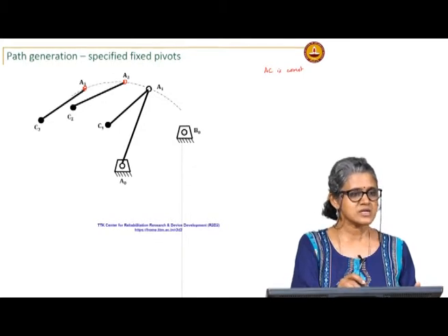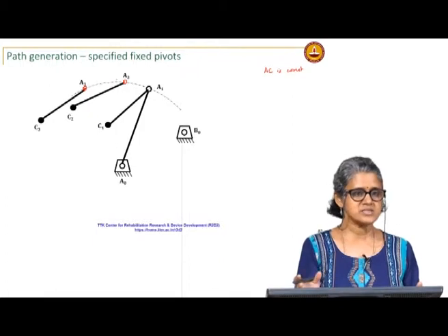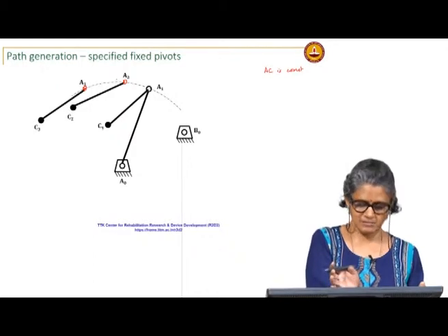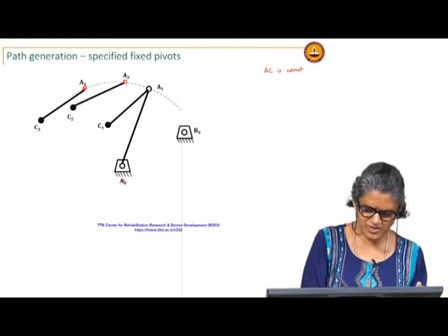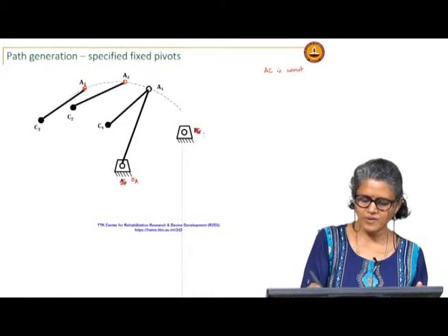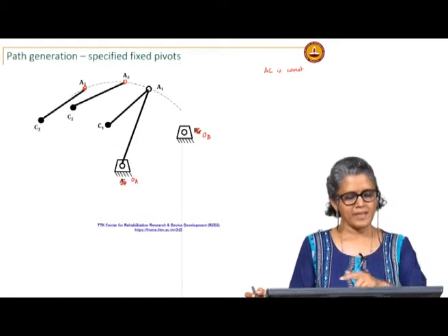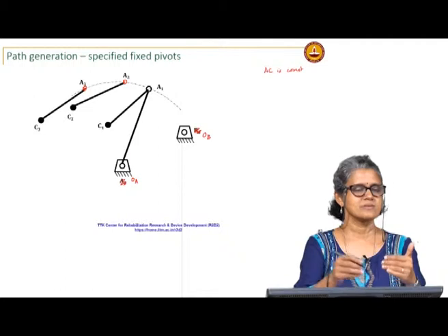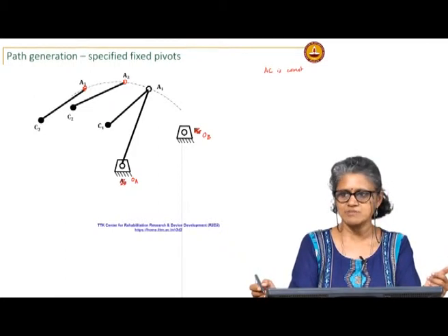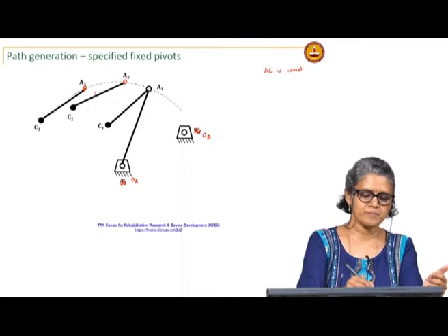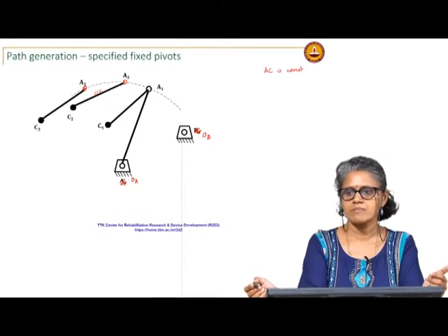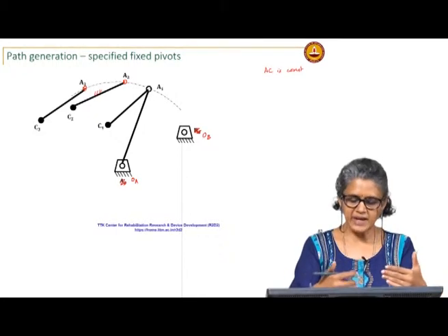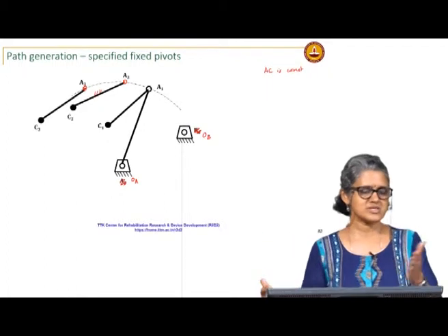If I sit on A2 C2, then I transfer the relative locations of A1 C1 with OA and OB. I should just go with the same OA OB. And then for the third position, put that with respect to the second position, if that is the position that is not moving. So, I could sit on that, invert the mechanism, find the relative locations of OA OB with respect to those positions.